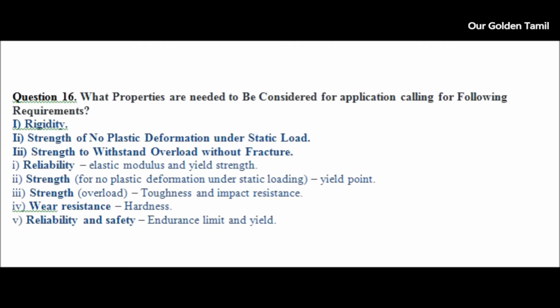Reliability, elastic modulus and yield strength. 2. Strength, for no plastic deformation under static loading, yield point. 3. Strength, overload, toughness and impact resistance. 4. Wear resistance, hardness. 5. Reliability and safety, endurance limit and yield.